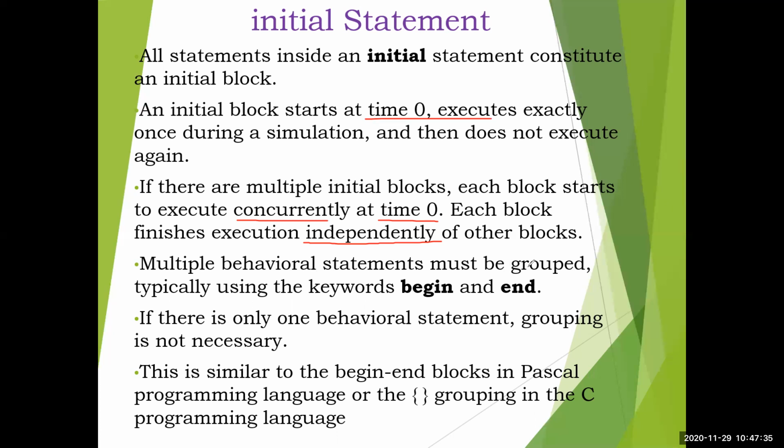Multiple behavioral statements must be grouped, typically using the keywords begin and end. This holds good in all the behavioral constructs from now onwards. In initial, if you have a single statement, for example in the previous stimulus module where we wrote the monitor statement, it was a single statement.